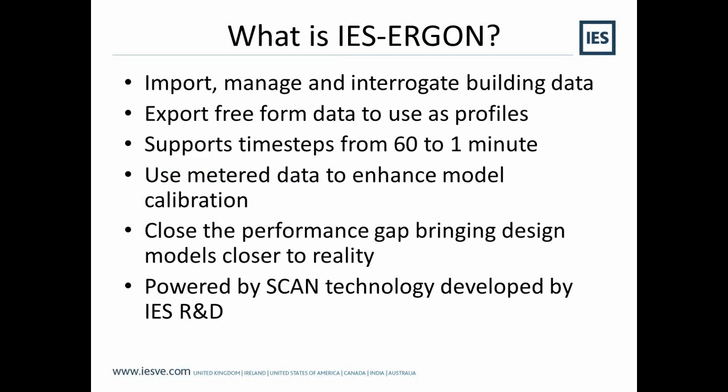The FFPs can deal with time steps from 60 minutes, 1 hour intervals, down to 1 minute if need be. You can synchronize that with your Apache simulation time step, so maybe typically 10 minutes, maybe 6 minutes.